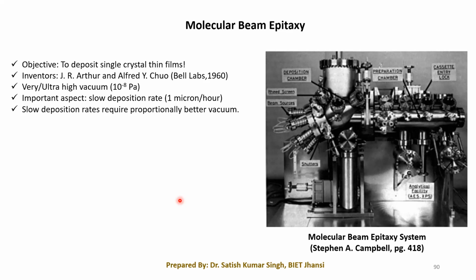The electron beams strike the silicon, heating it up to its melting point, and eventually it evaporates, forming a beam of silicon atoms that is directed towards the substrate. When the temperature gets down, it cools and condenses, and after condensation the silicon atoms are deposited over the substrate, onto the wafer surface.